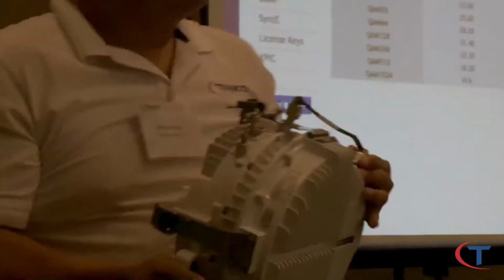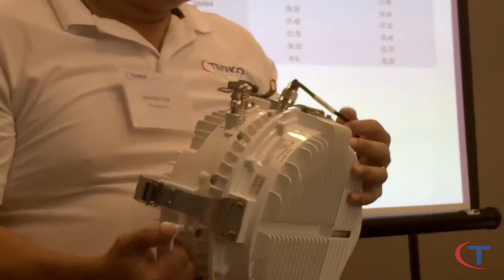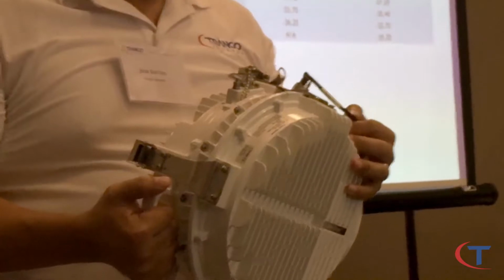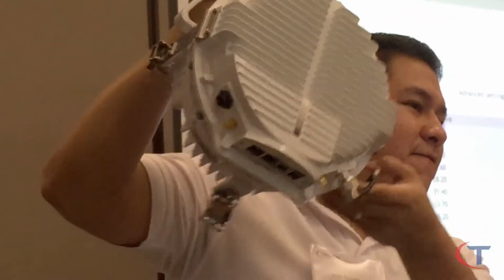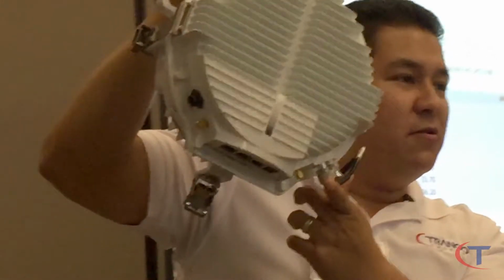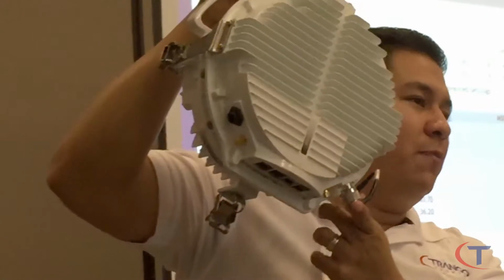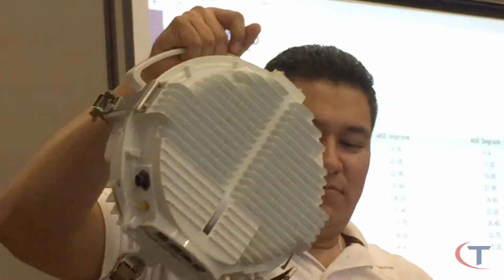And it's funny, but I've seen this cable on RMAs be totally bent or stripped because the installer on the tower decided to grab it to move the antenna around. And this is actually an IF cable. This is IF frequency coming through here. So instead of that big LMR, it's just a short jumper, but this can easily get damaged as well if you use it as a grabbing handle. So you should be able to grab it by this.